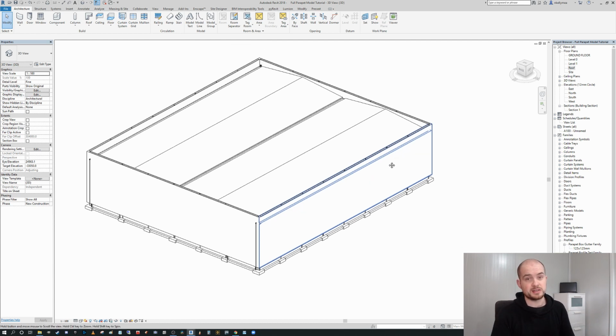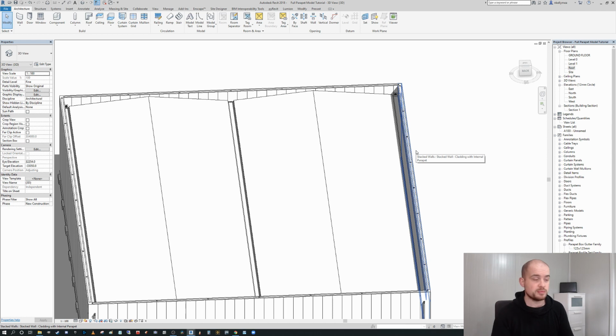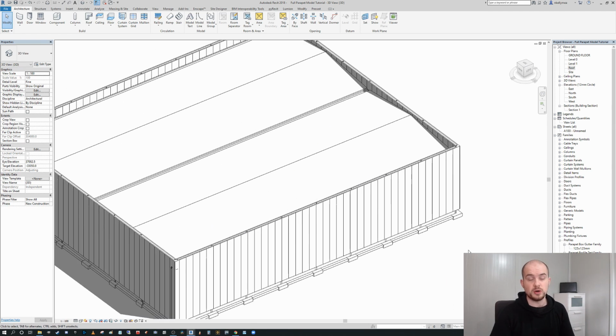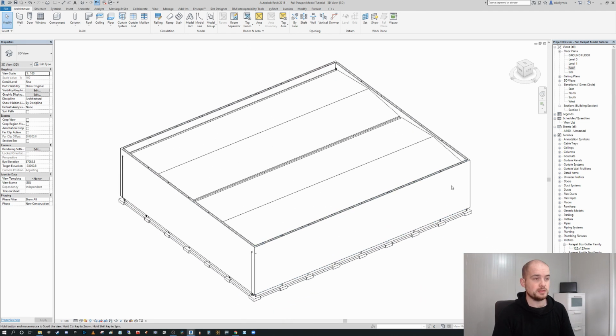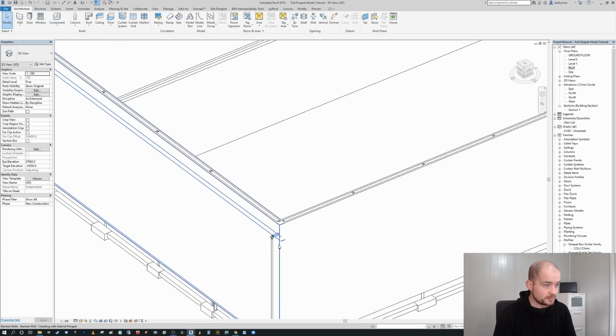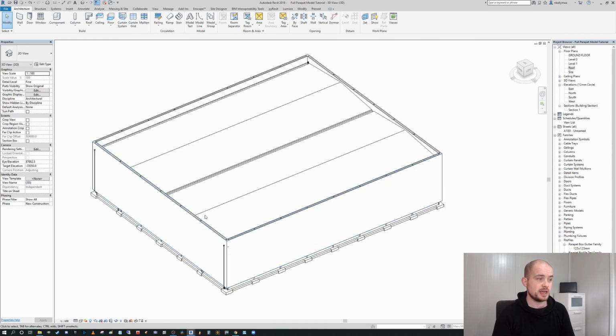The only way I can really suggest modeling them is to create smaller roofs to falls within the gutter footprint. I actually personally think that's over modeling, but look, it's up to yourselves. You can just use a notional element that will dictate what you want the falls to be, and you can put in the manual value on your plan view. But now we've actually closed out our first pass of our roof drainage.